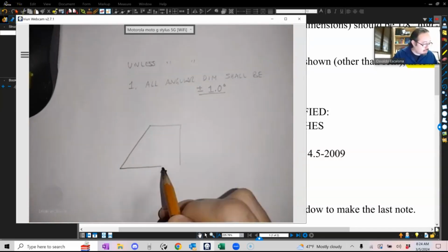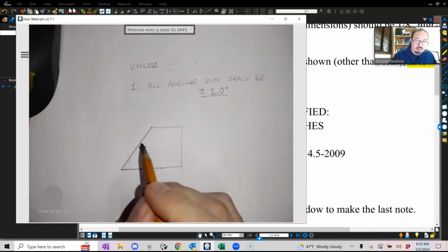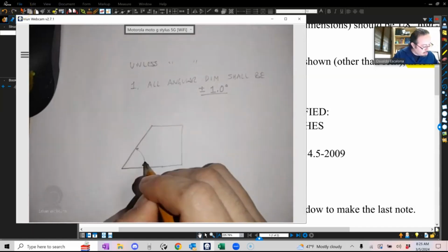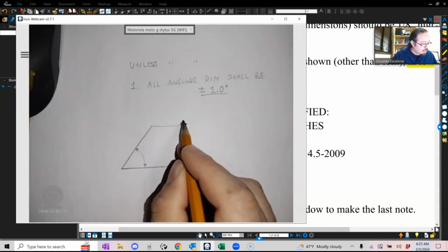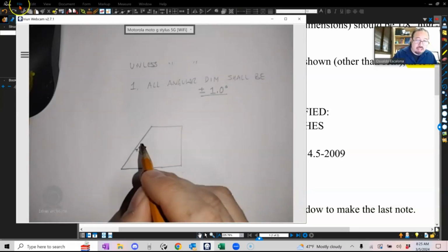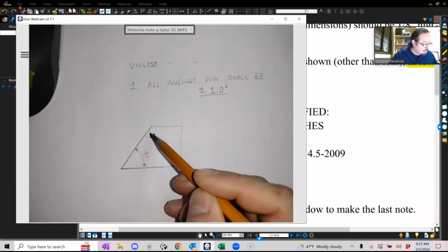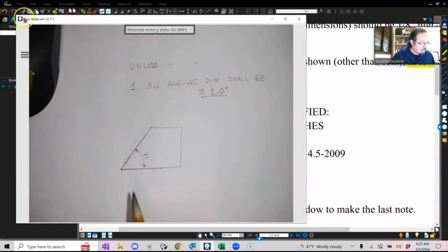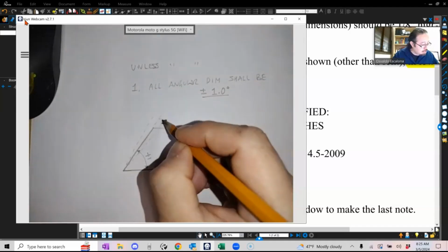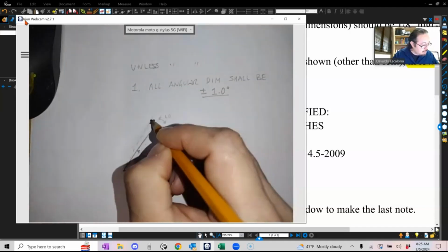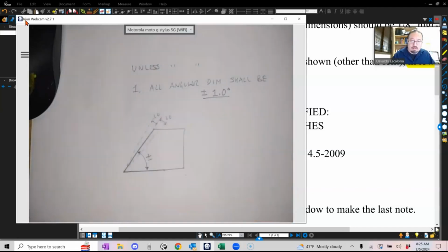Let's make the box like that, something like that, and it has an angle. You're controlling the dimension not by measuring from here to there, you're just measuring the angle. You will have a plus and minus on the angle. I mean that this guy could be here, we could be there, right? So let's call it 1 degree, a little bit bigger, less, 1 degree, a little bit more, right? Kind of like a variation in angle.